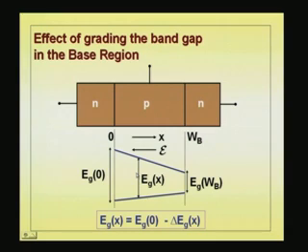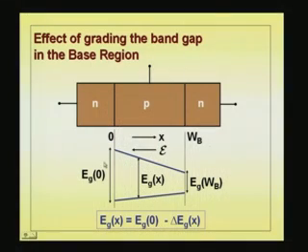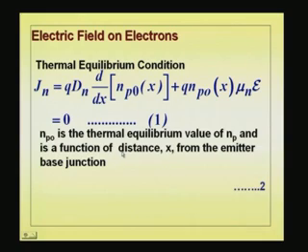In fact, we will come back to this if we have time to see the physical meaning of this, but right now, from the diagram itself, you can see there is an electric field like this. Whenever there is a band gap changing like that, the field is plus on the lower energy side and minus on that side. Now, let us go back and see what the magnitude of this field is. Very quickly we will rush through that.